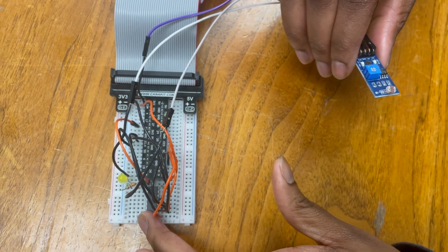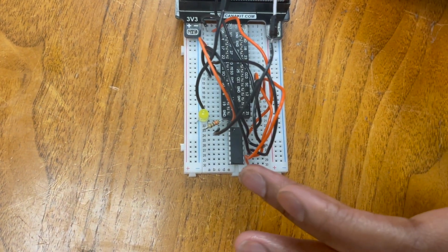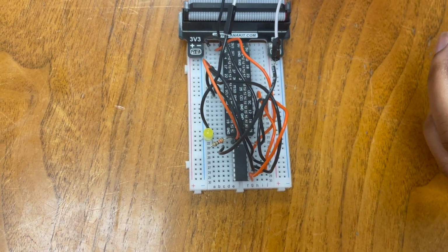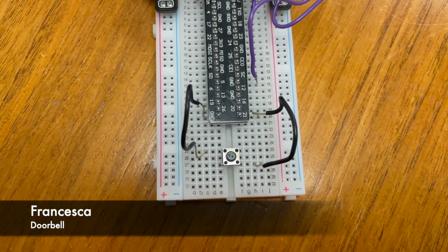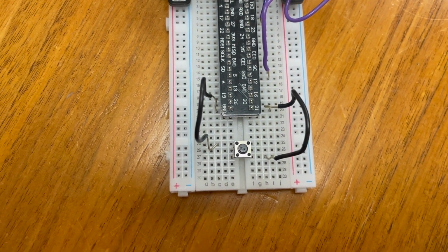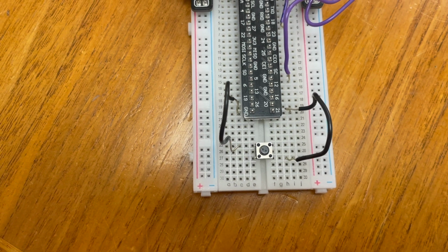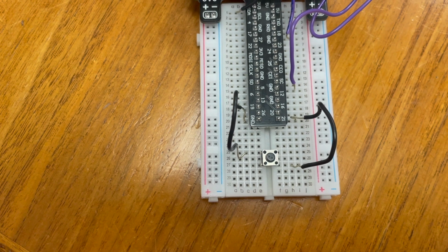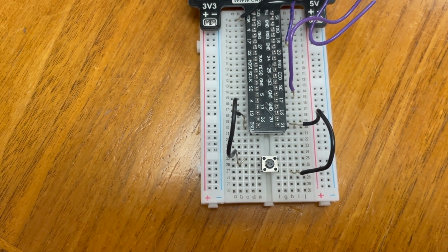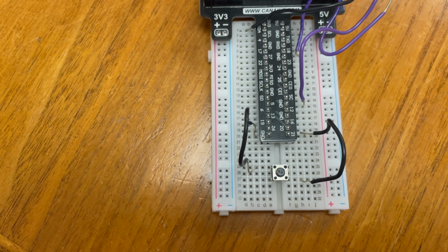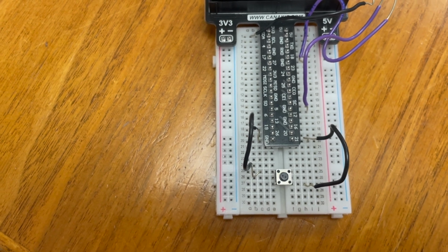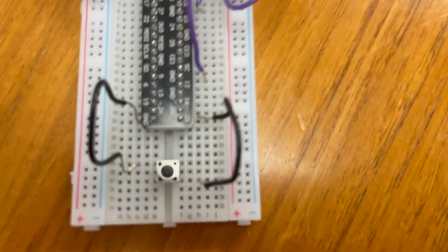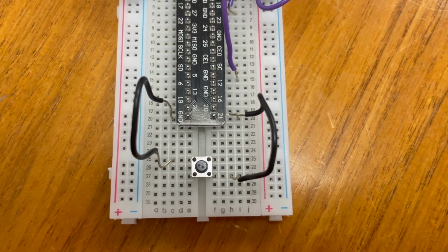So the ADC enables me to convert all those things to voltage, so I'm able to view those values. To implement the doorbell, we are using a button from the lab connected to a specific pin on the Pi and ground. A button press represents a visitor ringing the doorbell. From the Python library GPIO Zero, we are using the class Button. Specifying the pin it is connected to and then calling its provided methods is the only other step. In this case, you would specify pin 21 and see that it's connected to ground.